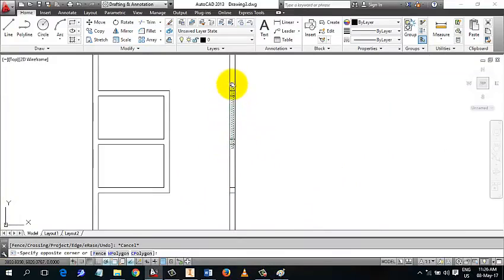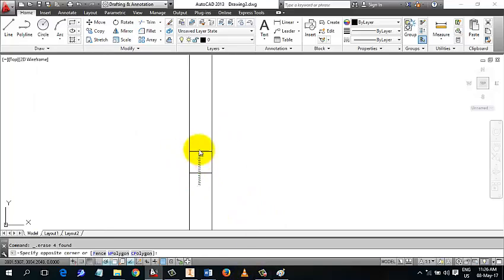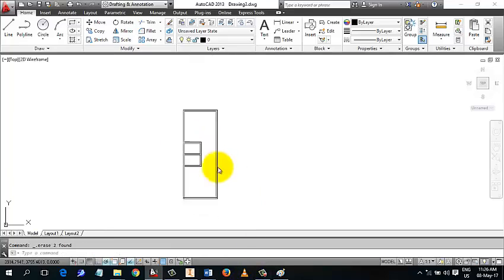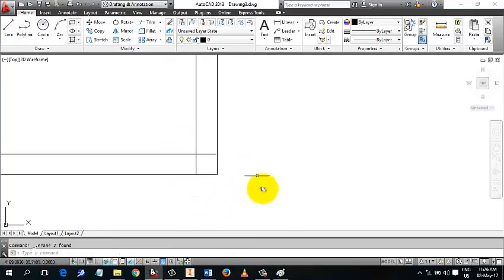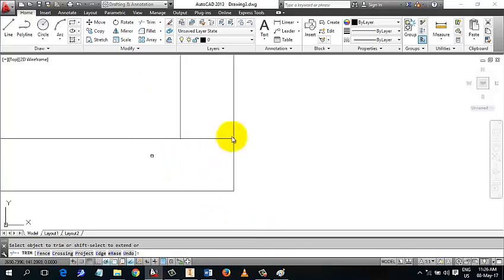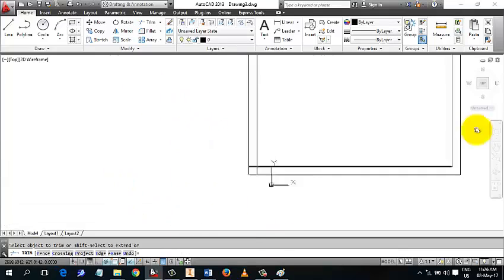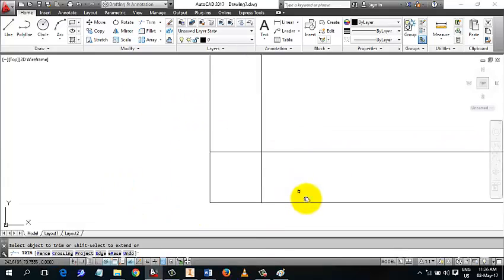So I'm using cross selection inside. Press delete. See? You delete that. Okay. I still need to do trim on. Enter. Trim. It's trim because it's cutting an edge. Are you getting me?